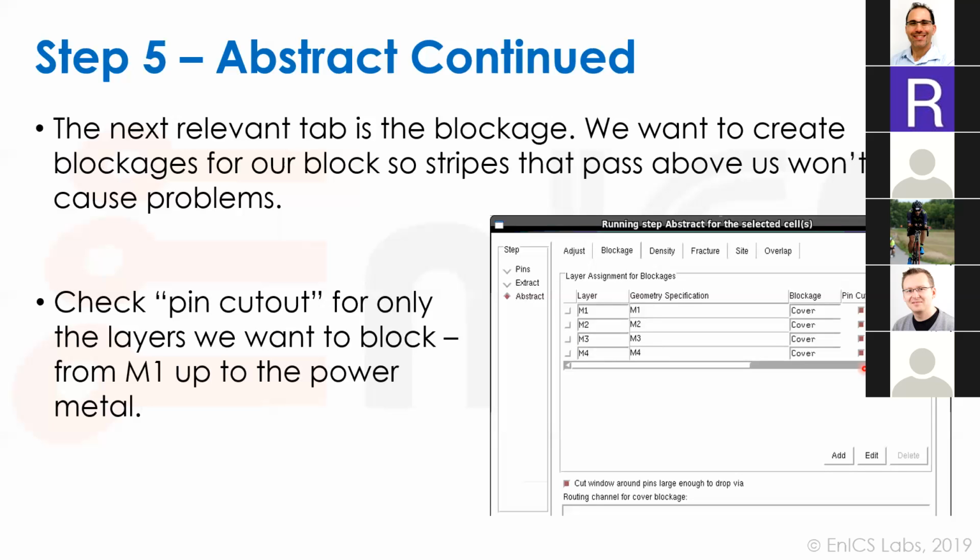When there is, for example, no track alignment, it could do some crazy vias and DRC. So these cuts do not help, at least for the digital pins, if the digital pins are on the boundary. Okay, so I'll try to generate a new LEF for you anyway that I need to provide you, and I'll try it with the pin cutout you just said.